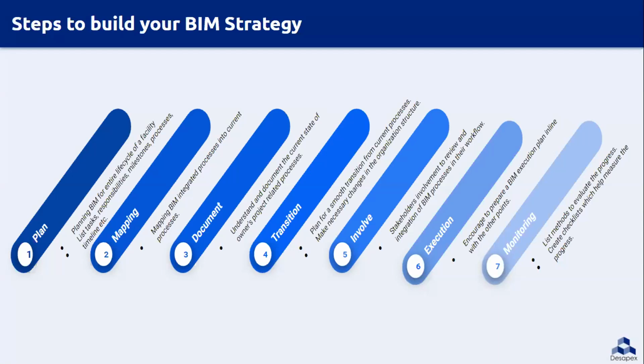List down the tasks the owner organization should perform for the success of BIM. It might be training, setting up systems, process guidelines, etc. Set a matrix which defines responsibility for communication, escalation, review and approval of BIM models. Setting a milestone for deliverables at the initial stage of the project is very important for clear understanding and delivery of the project at required intervals.